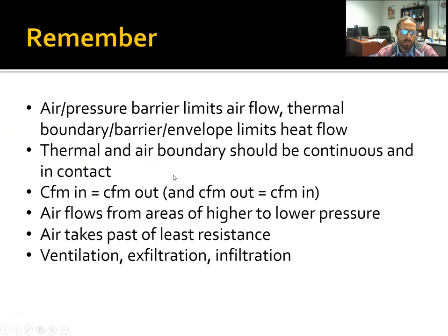This is a reminder from the previous presentation. Remember that an air barrier or a pressure barrier limits airflow, and that a thermal boundary or thermal barrier or the envelope limits heat flow. Okay, we want to have a good, efficient building. We'll have a continuous thermal and air boundary over the entire building envelope.